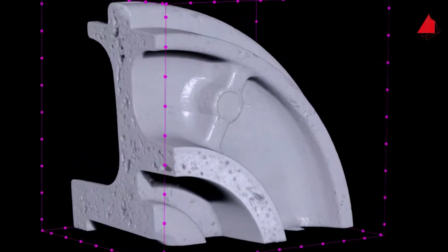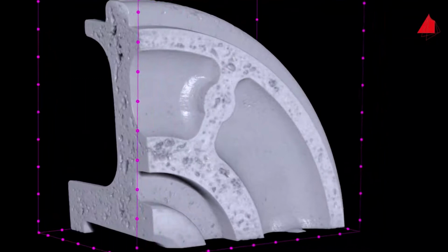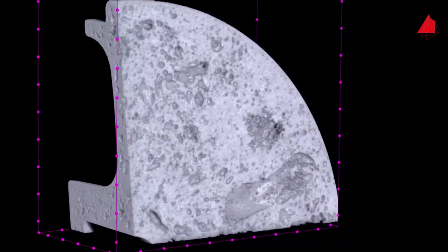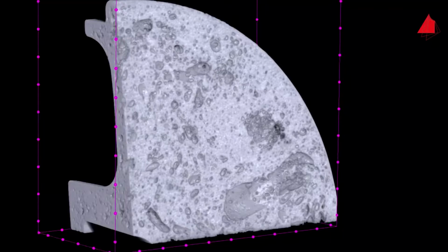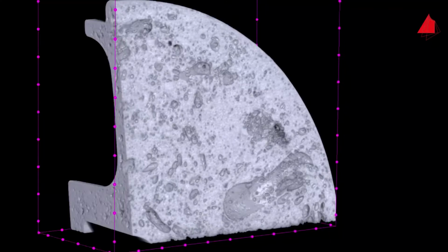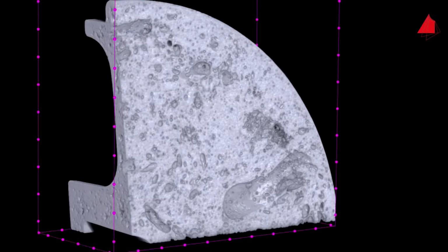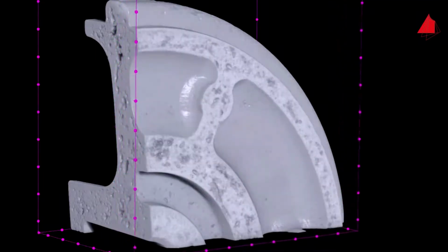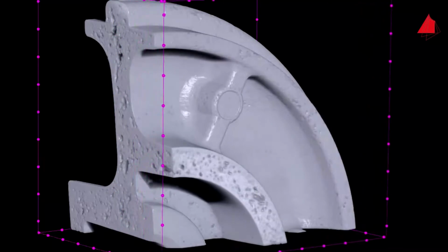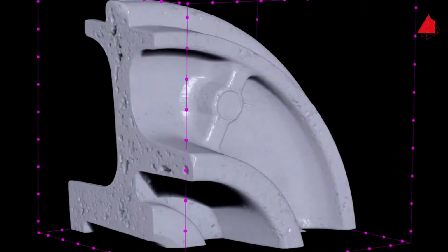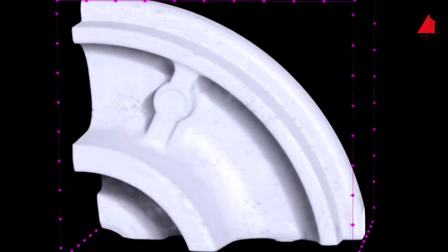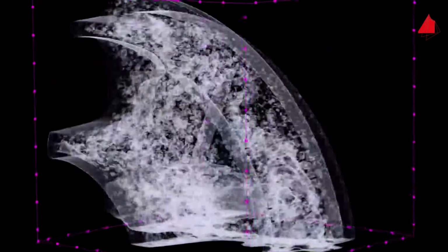Many pores of different sizes can be seen. The pores are filled with air that has been trapped in the course of the die casting process. The venting of the die has not been good and has led to a great number of large air inclusions. If preferred, the material can also be visualized transparently. Then the defect surfaces appear bright.